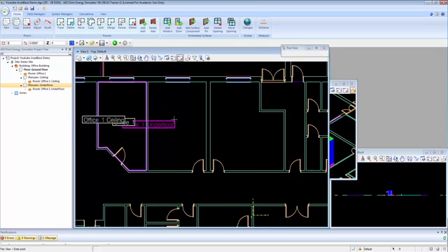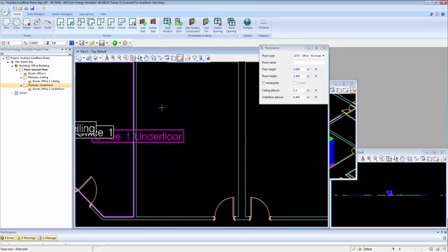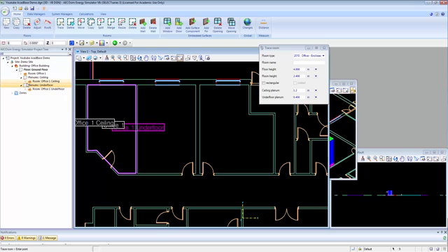A couple of things I want to note here. If we close the plenum space and have a look under surfaces, it has everything down as exposed walls because it doesn't recognize anything else around it. So I'm going to create another room here. I'm going to call this one Office 2, and accept all the other defaults there, that's fine.